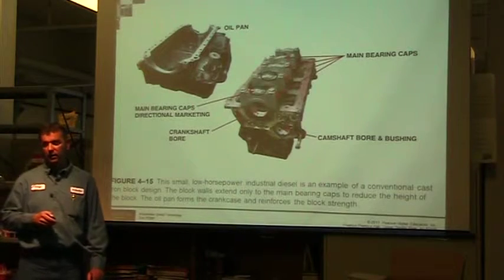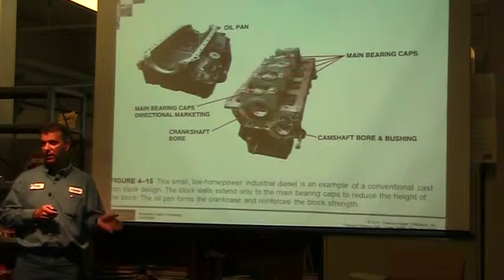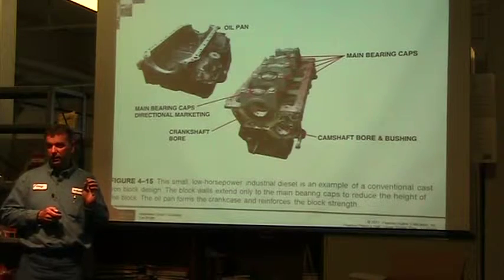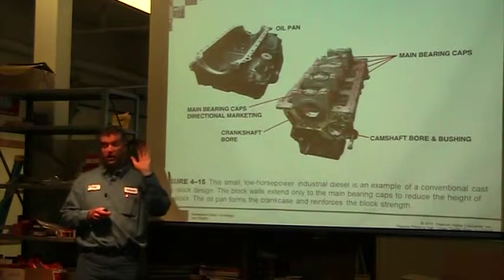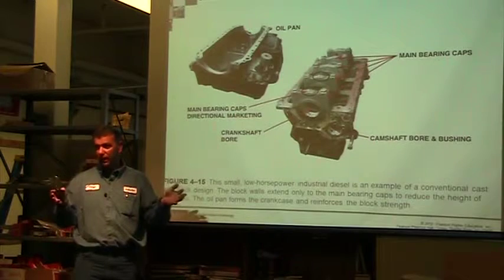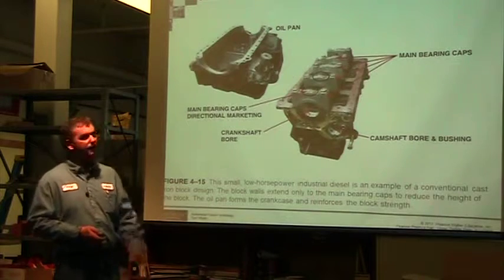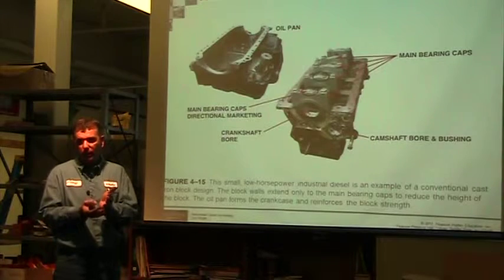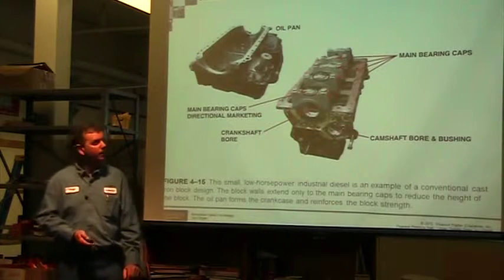So we bought a Yanmar engine that had one of these kinds of pans on it. We put it into a John Deere Gator. In the Gator application, it was less than 4 quarts. So it wasn't even a full gallon. And the pan that originally came on it was from a reefer unit. That unit had like 2.5 gallons. So there's a big difference between the two pans. So we definitely had to remove them and replace them. The Gator had very little room for an oil pan. The oil pan had to be really small just to fit in the application where it was at. So a very small amount of oil.